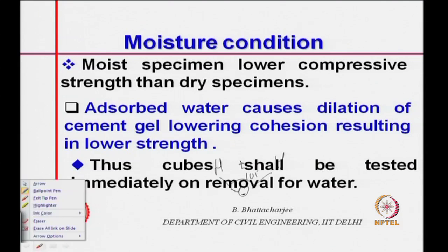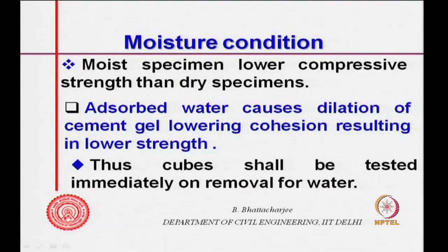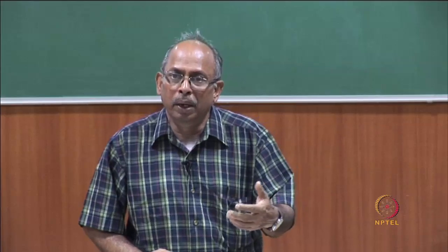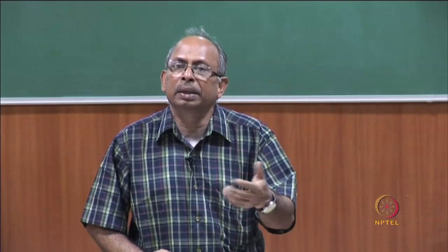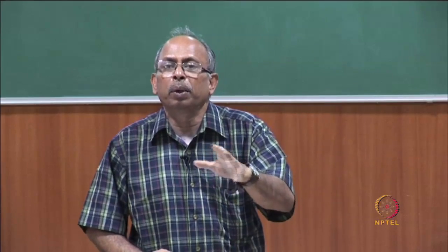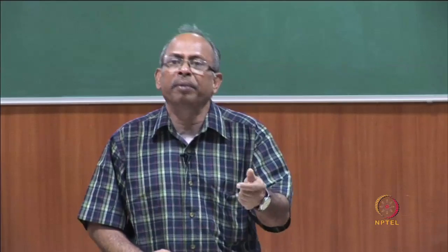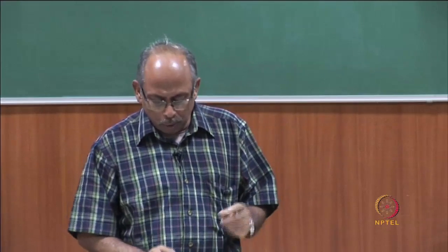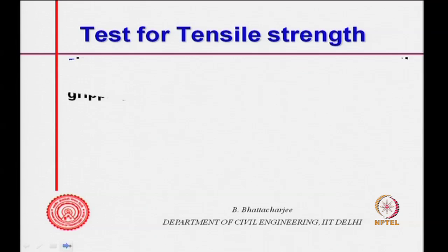So, cubes are to be tested at a standard moisture condition. You have a saturated surface dry situation, and the code tells you within how much time you should wipe off the surface and then test it, and how long it can be exposed, and within how much time you should be testing. So, moisture condition is an important issue. So, that is what we have.